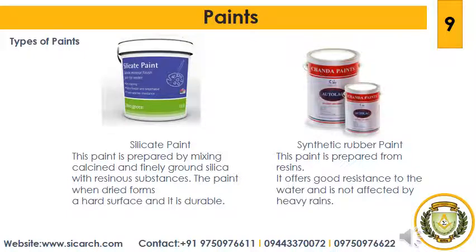This paint is prepared by mixing calcined and finely ground silica with resinous substances. The paint when dried forms a hard surface and it is durable. It can stand extreme heat and it adheres firmly to brickwork also. It is not affected by alkalis. No chemical reaction takes place on metals by this paint. The dryer used in this paint should be of special silicate dryer type.